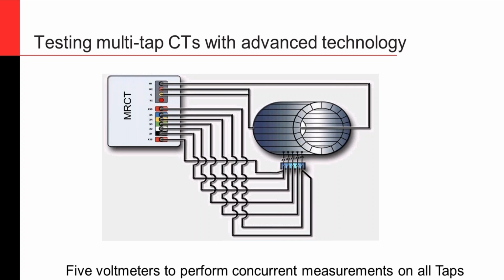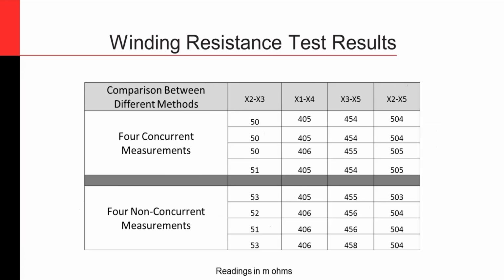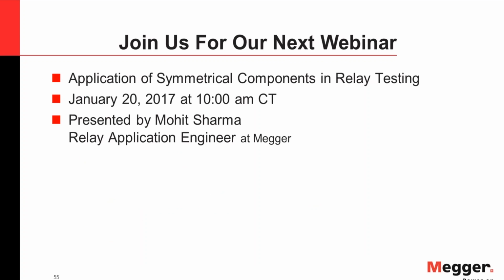Sometimes when you look at a CT, it is typically made of an iron core, and it starts to magnetize after a while because of high current or various other reasons. Off the top of my head, I can think of high current because of any fault. So the primary reason for the ratio accuracy to differ is magnetization, and I would also add disintegration of the leads, the insulation of the leads.